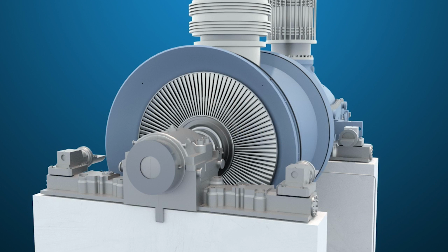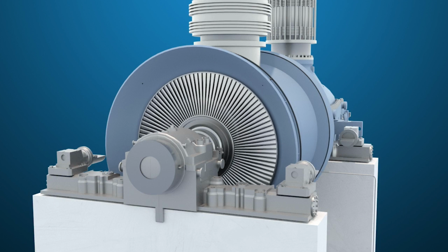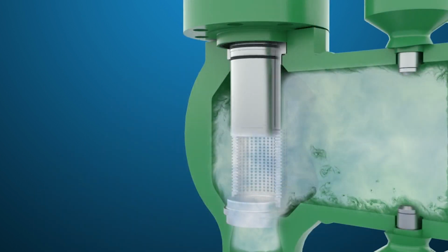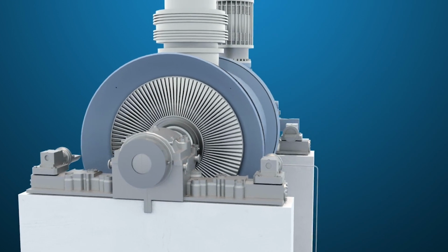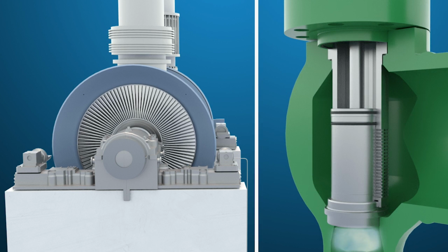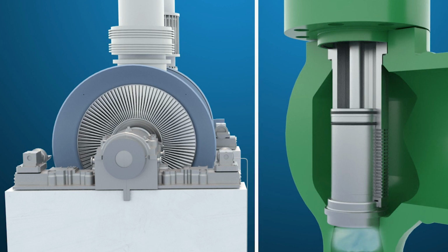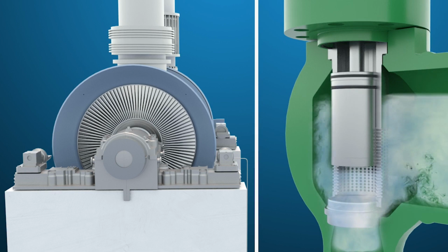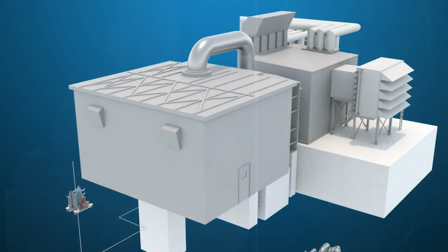During startup, the bypass valves will maintain a pressure set point necessary to roll up the steam turbine. The valves open and close as necessary throughout the startup. Also, during the blending process, when both steam plants are connected, the lag unit bypass valve set point is adjusted to match the running unit, equalizing the pressure across the header block valves, allowing them to open.